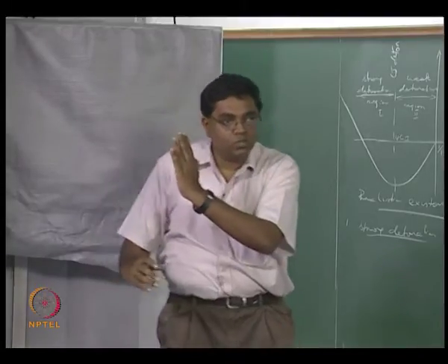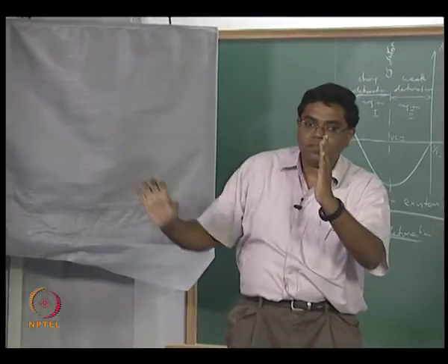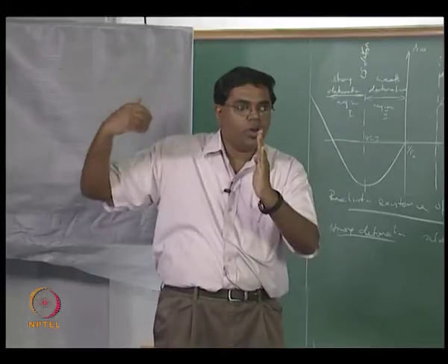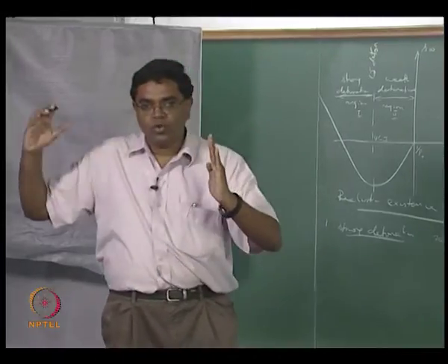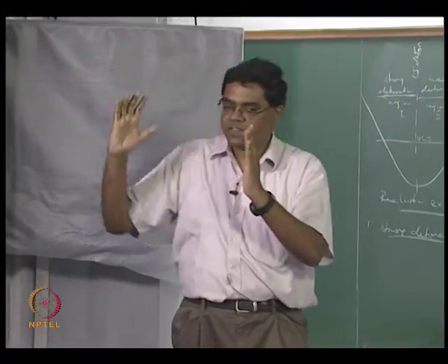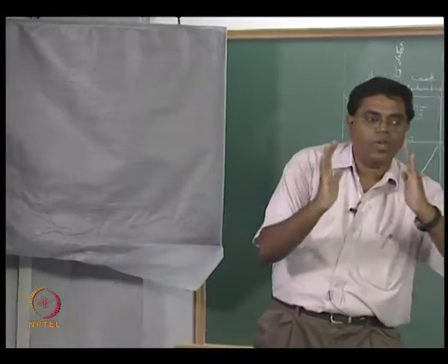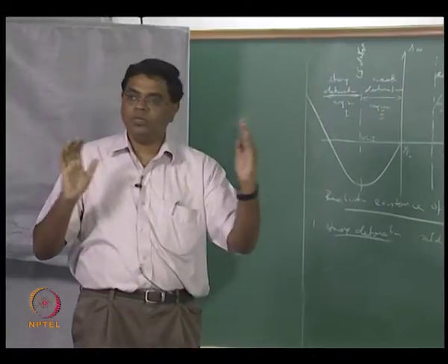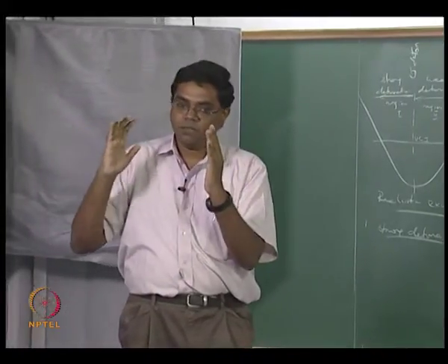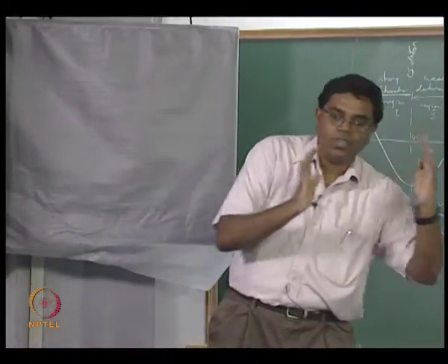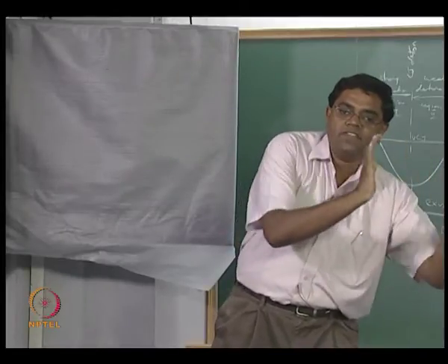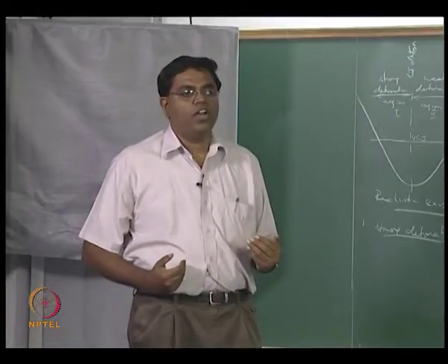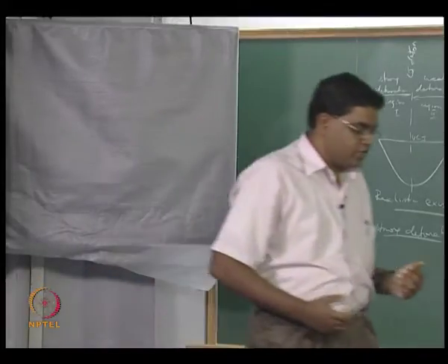But the moment the detonation wave begins to propagate, this space is vacated, right. So you can't really have the pressure hold on until you are able to actually have this confinement follow the wave, right. So this is what's called an overdriven shock tube. So that means you have to have like a piston that runs along with the wave and keeps this confinement as it is in order to be able to preserve the very high pressure that's been obtained with the strong detonation.